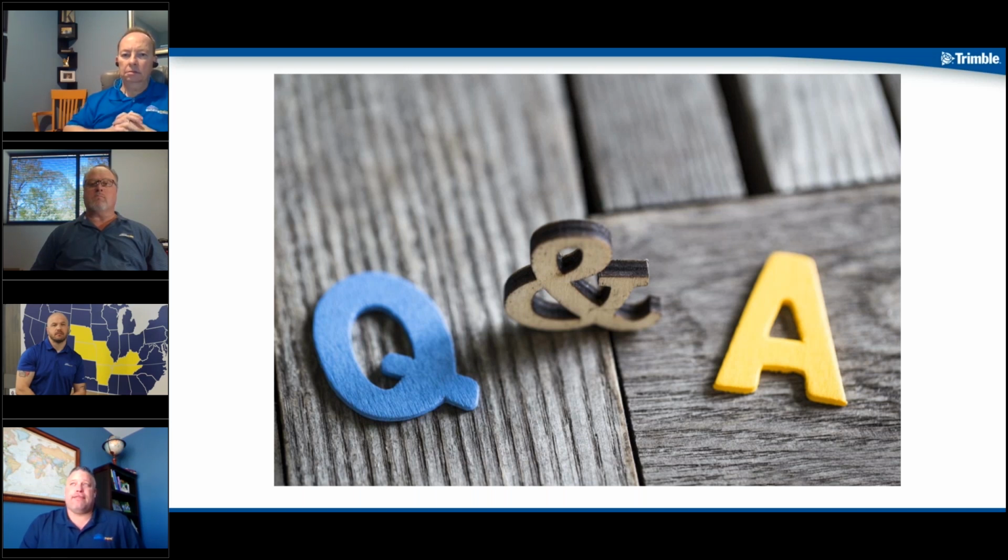Sure. I mean, if you could set up on the radius point, that would be ideal. But that gives you that third piece of information that you would need, right? Because then you would know your radius distance. You would know where your point of curvature starts, or point of tangency, and then you could use that and backtrack it over to the next point, or the wall, or the footing, or whatever it is that you're trying to lay out. So to be able to lay out a curve, you would need a few points of information. If you don't have it, you've really got to make a phone call and call somebody to find it. Yeah, gotcha. It's risky to fake that.